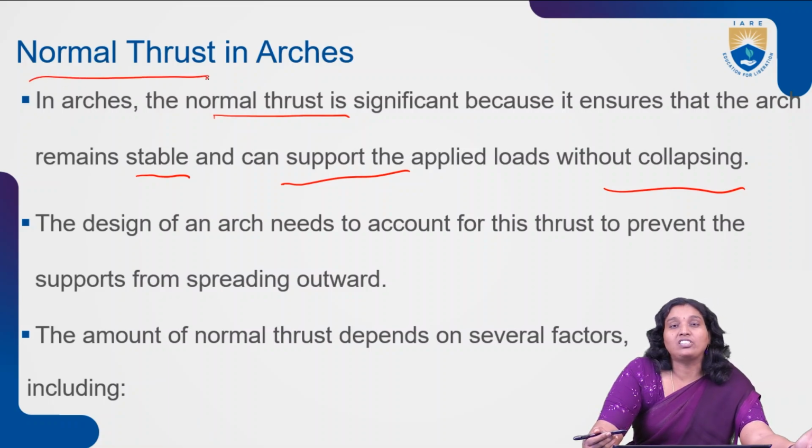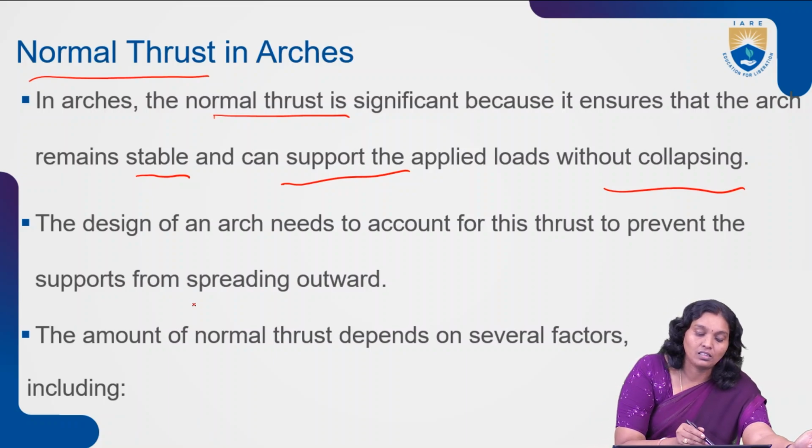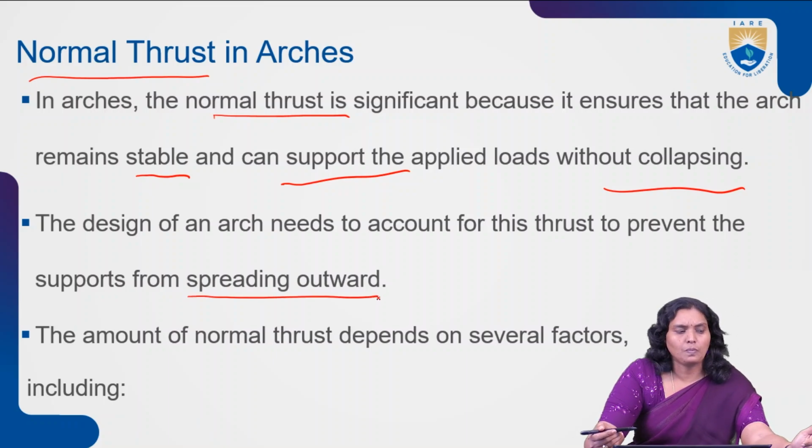The horizontal component of the reactions is important for better understanding of arches at the time of their analysis, and in the design part also, this normal thrust plays a role. The design of an arch needs to account for this thrust to prevent the supports from spreading outward. So why is this understanding required?